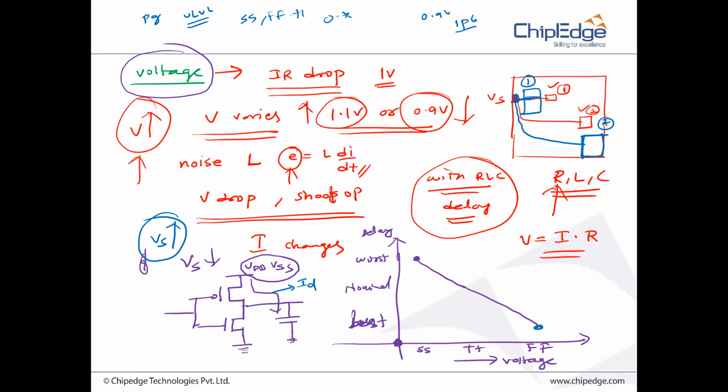Floor planning looks very easy and very simple, but that is the heart of the design. If you don't do better floor planning, everything will be gone. Your congestion will be more. Finally, timing violations will be there, and you need to reduce these violations. You need to add some more cells and all. Area increases. So many things will be affected. Is that clear, guys? Yes, sir.